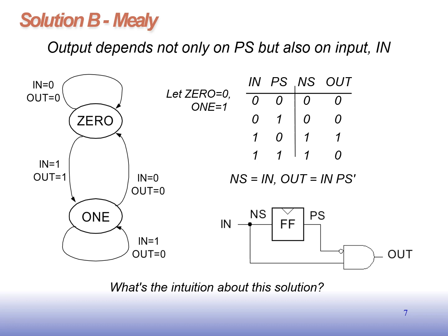Okay, here that 0 you take as state 0, 1 you take as state 1. From the state diagram, draw the state table. So if you look at that, the next state is similar to the input. The output is the inverse of the present state. Okay, so using this, draw the diagram.